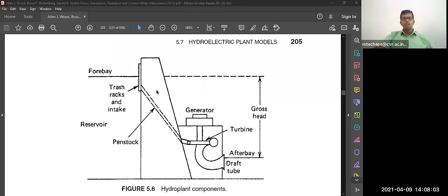As I already said, the valve house depends on the amount of power generation in the particular generator. Say you want 100 megawatt, say you want 200 megawatt. Based on that, in the valve house, they will open the valve fully, or partially, say 3 by 4 open, depending on how much pressure and velocity you want for hitting that particular turbine.